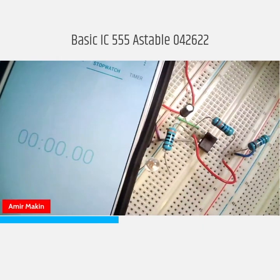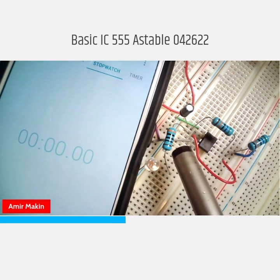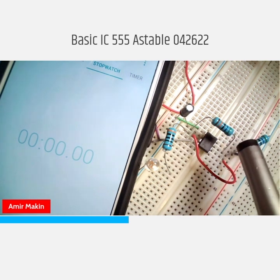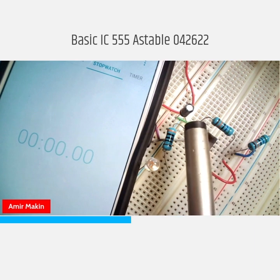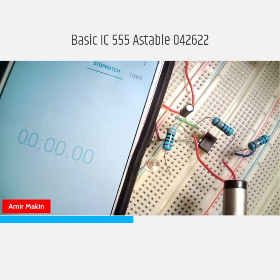All right. If you can see here, we've got our timer that we're going to turn on once we turn the battery on. You have your light emitting diode that's going to indicate how long the pulse is. We have our 560 ohm resistor, which limits the current. We have our 560K resistor here, and our second 560K resistor here. Then that goes down in series with the 10 microfarad capacitor here. Here we have the 555 timer chip, and all of this is connected and configured the same way that we showed you in the circuit.